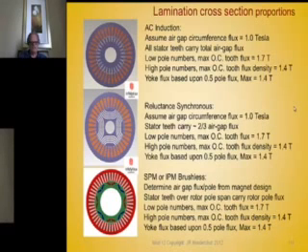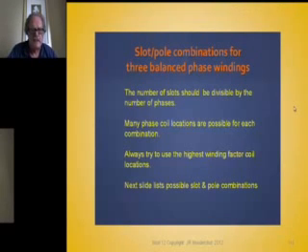For a permanent magnet machine, the flux is determined by the flux per pole from the permanent magnet, so there is an open circuit tooth flux density there. The teeth that span an actual magnet pole carry that rotor flux, so some of the teeth in between the poles don't carry any rotor flux at all on open circuit. The bottom line, I think, is that the same flux density guidelines can be used.